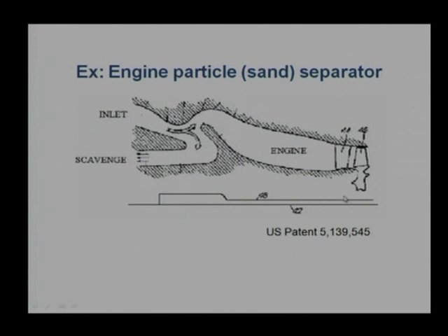There is one patent which was filed in the USA in 1995. You can see there is an inlet change in design, there is an inlet suction, and we are generating a hindrance. So, the particle can come and impinge on this at an angle of almost 90 degrees. After that there is a parallel direction change, and the direction is parallel to this. So, I can use this as the proper design of material. Of course, the design is already there, we can choose a proper material which has a high impact angle, and the air has a skew route also. As there is a change in curvature, the particle will not be able to climb that much.